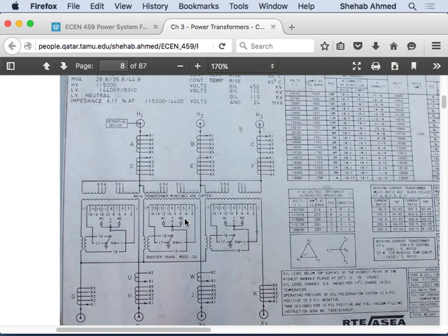Then I can put a huge power system in front of me as an engineer, and I can, for example, put a color indication on PowerWorld that says, if the voltage in this region is less than 0.95, for example, change the color in this zone to something else, right? So we will have to do stuff like that. And the voltage, as I said, because it is changing all the time, the utility needs to make sure that it knows that this is happening and is controlling the voltage around the system.